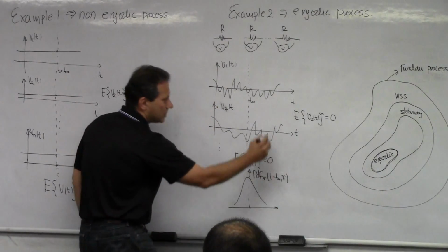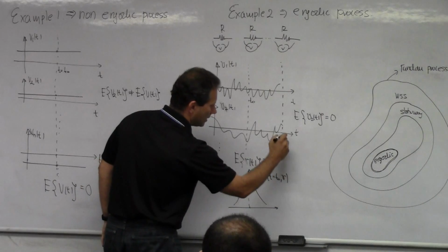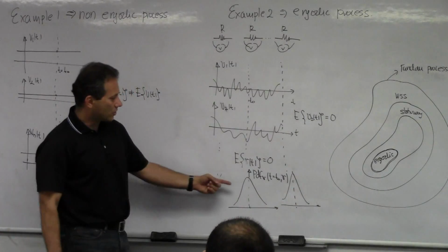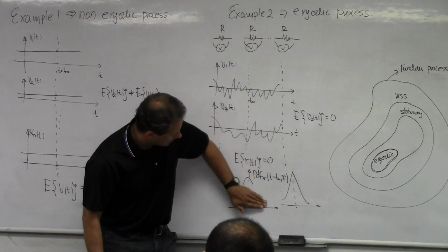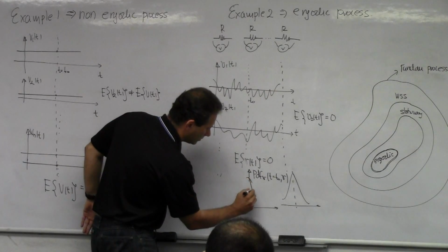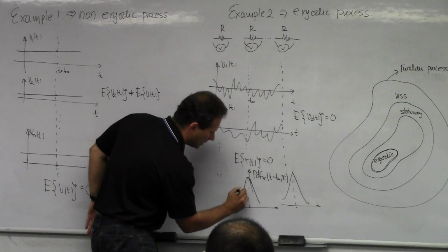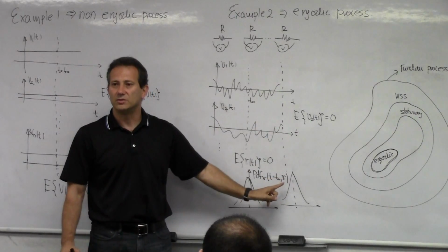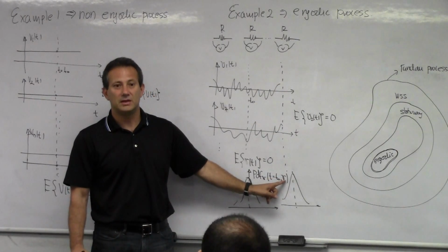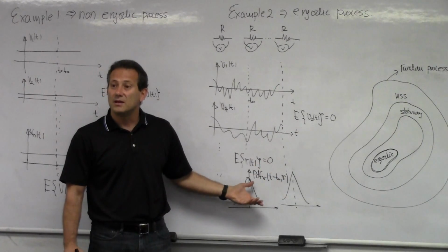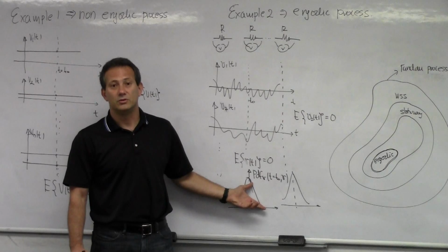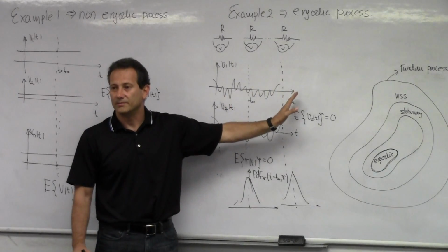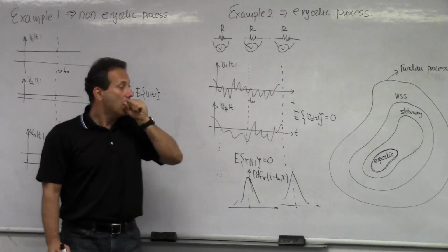Now, I change time, and I look at this different time, and I do the same experiment. I determine the PDF again. The way I draw it is probably not good, because I drew them as different, but what I wanted to say is, think about the reality of the situation. If these resistors stayed at the same temperature, what would be the reason for this PDF to change? There will be no reason, right? So the PDF is the same. That's an example of a process that is stationary in the amplitude domain, because the statistics of the amplitude distribution do not change over time.